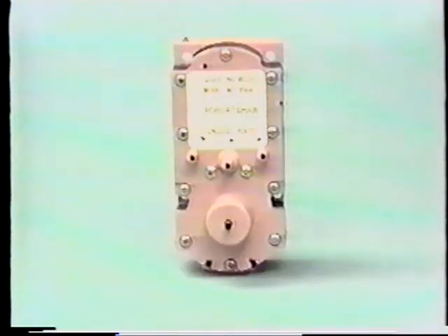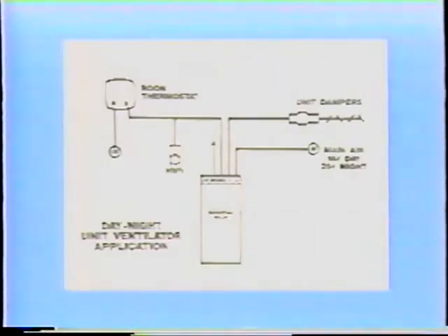This device is a non-adjustable diverting relay. It is a snap-acting device designed for switching and interlocking functions in a pneumatic control system. It may be used to feed or exhaust branch lines or to divert one or two air sources to a single device. These relays should be used only where a positive change in signal pressure occurs, such as main air in summer-winter or day-night changeover type systems, or with a two-position pneumatic signal.